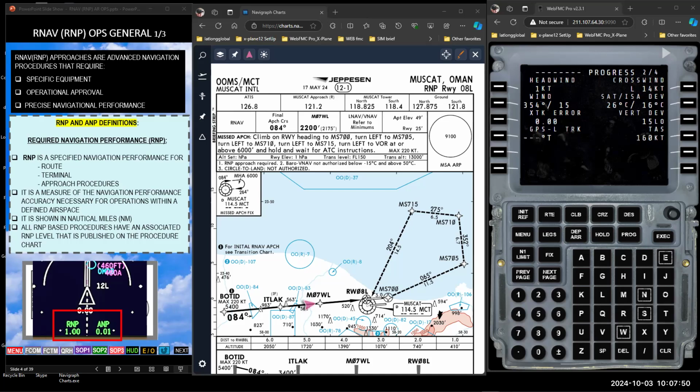And radio altimeter, of course, was alive, and that call didn't come because I'm busy on the flight deck, but remember, all the calls are very important. And the radio altimeter alive and for your position compared to the barometric altimeter, and providing the altimeter setting was correct, and providing there were no corrections required because of temperature, then your pilot thinking is, yes, acceptable. All those things I talk about in my library and are important, and they come under airmanship.